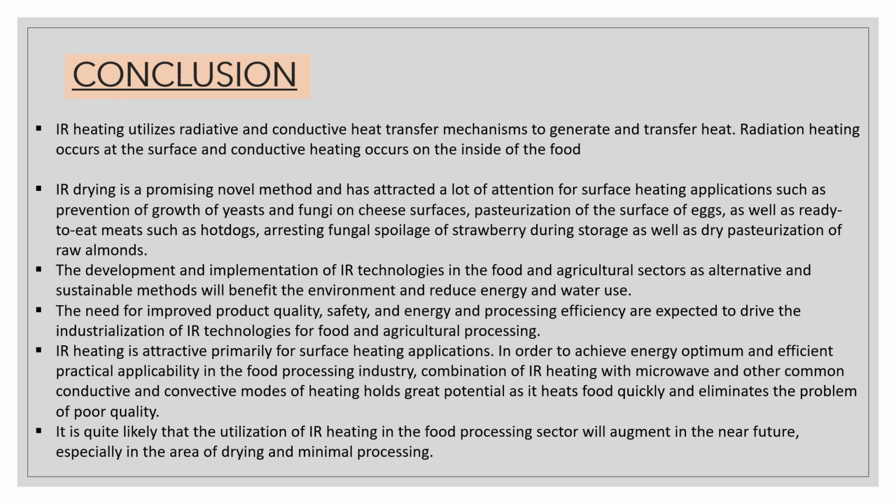Combination of IR heating with microwave and other conductive and convective modes of heating, such as hot air, holds great potential as it heats food quickly and eliminates the problem of poor quality. It is quite likely that the utilization of IR heating in the food processing sector will increase in the near future, especially in the area of drying and thermal processing.